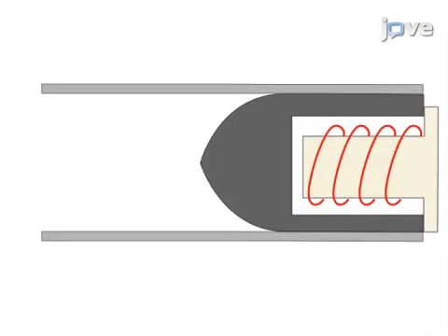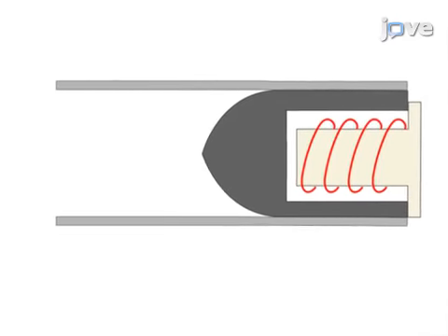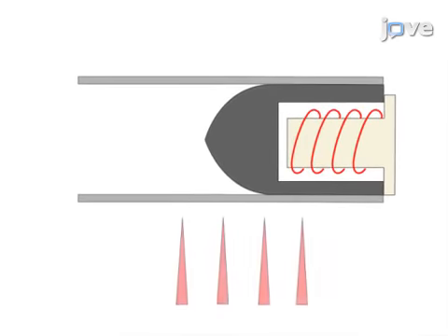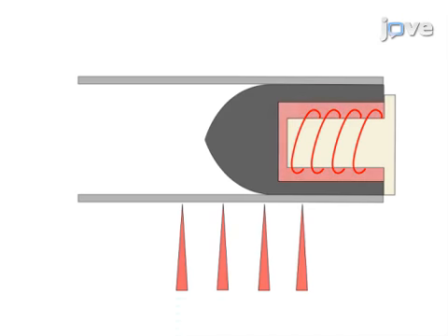As a second step, the target cylinder is then mounted concentrically to the end of the gas gun barrel, and laser-based velocimetry diagnostics are installed to measure the expansion velocity at several points along the cylinder, and high-speed imaging is used to track fracture initiation and growth. Next, the cylinder is brought to the desired temperature, and the polycarbonate projectile is launched into the target.